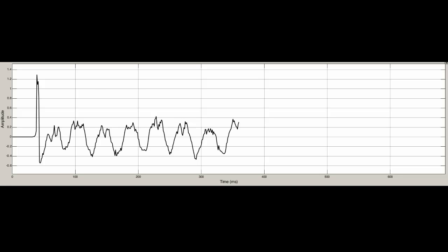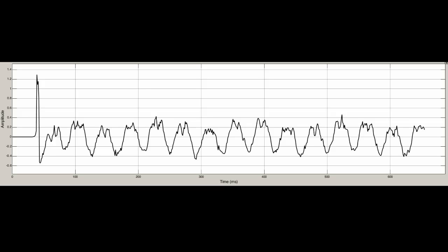So let us look at the time domain representation of the phase after unwrapping. You can see the phase variation after phase unwrapping of the desired range bin, and initially the phase has a transition because of the delays in the path. The phase is the summation of two sinusoids. Ideally, the largest period of the phase is for the first object, and the small high frequencies in the phase are for the second target. But the phase is not a clean signal; it is distorted by the AWGN, the phase noise and the IQ imbalances,